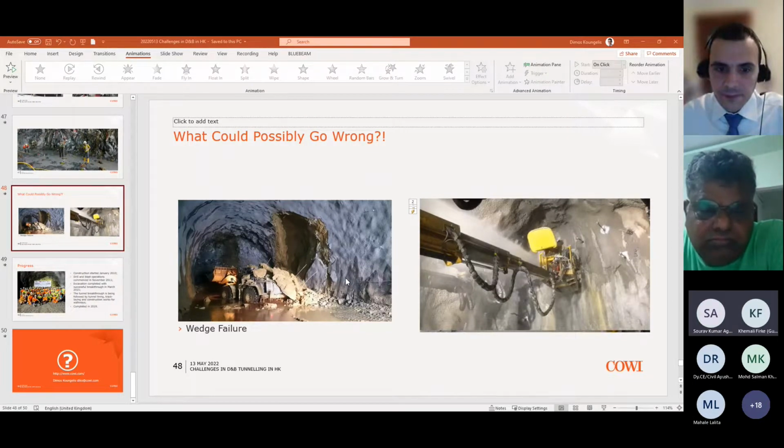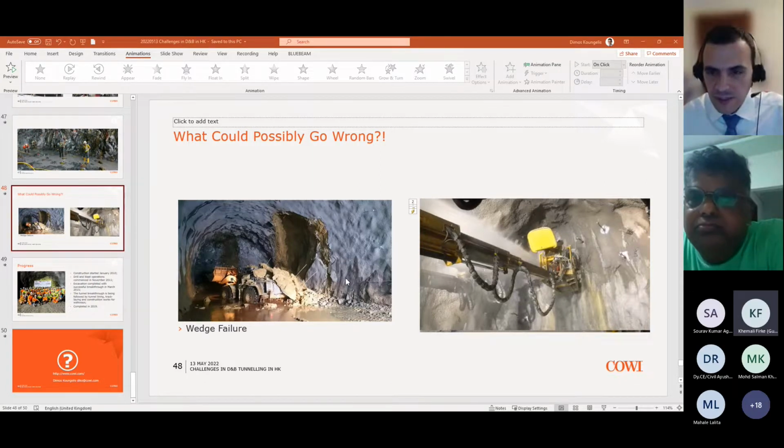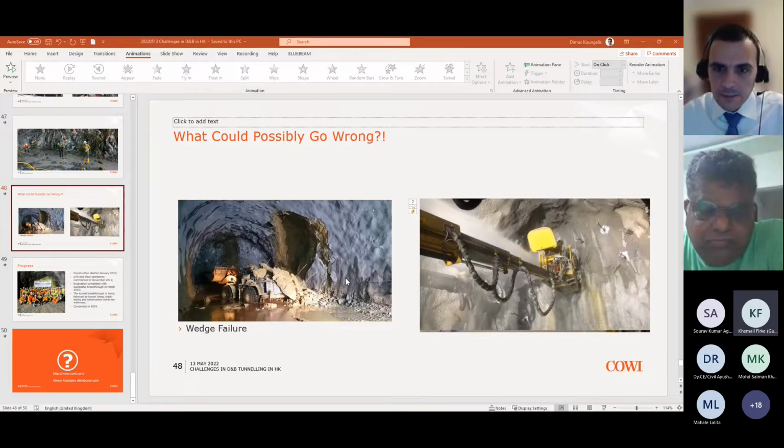Okay. He also has one more question. Was P wave velocity of rock taken? Yeah, so when we did our assessment, we used these empirical formulas that I described in my slides. We also did the P wave, the dynamic. We had some lab tests for the stiffness, and we came up with appropriate stiffness values for the different support classes. Okay.